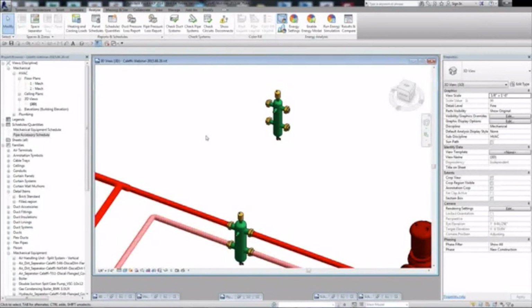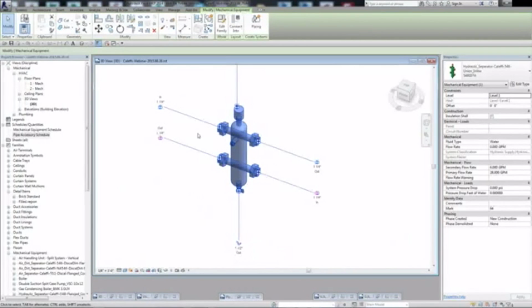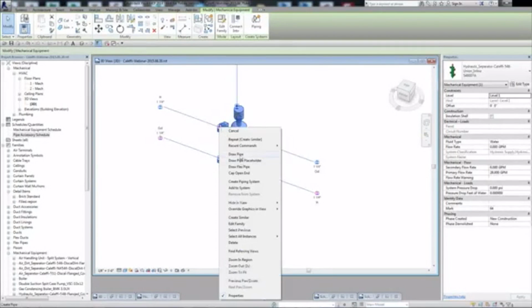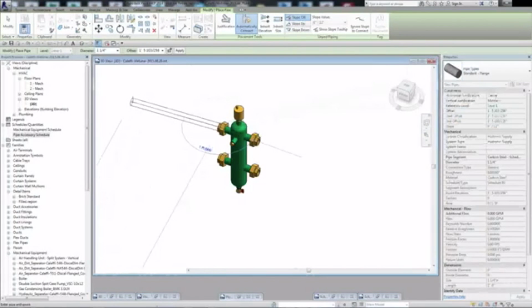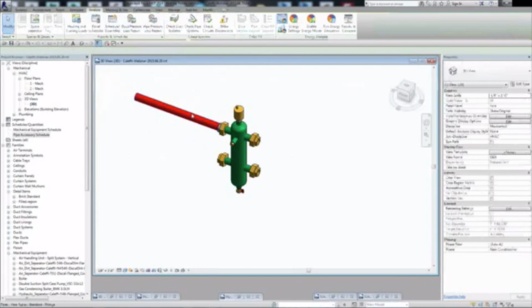Okay. Can you repeat the second part of that question? Different types of pipe. I think you said plastic or metal. Oh, okay. Yes. No, Revit doesn't. In this case, it's going to be a union inline. It wouldn't use a flanged pipe, but if I were to draw pipe, and then select a flanged size and put it on there, it will likely. Oh, in this case, no flanges are available for 1.25 inches, so that's good. But it would place a flange size.